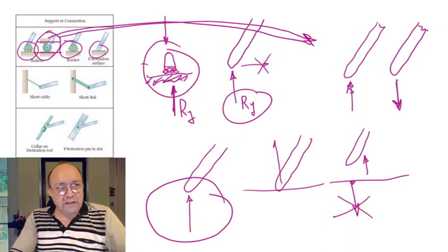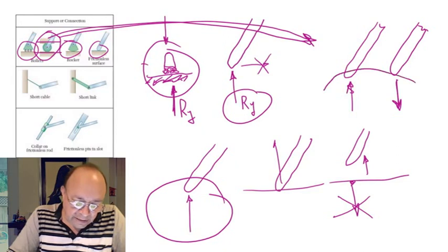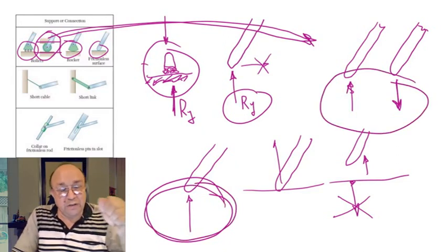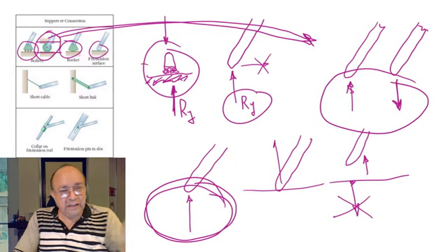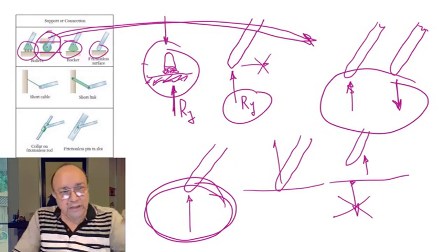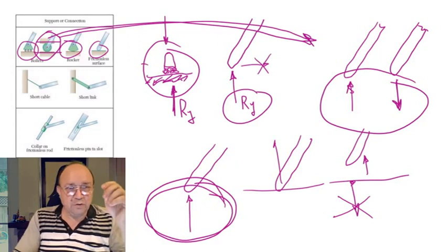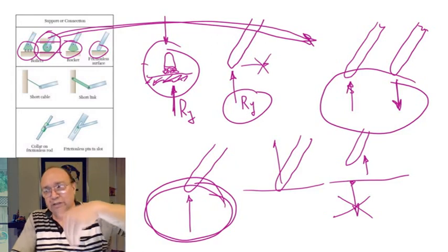That doesn't affect us much because since these forces are unknowns, when you set up the equations, you can put the sense of the force in any direction you want. At the end of the calculations, if you find that the result gives you a negative sign, you know that the sense you assumed was wrong, so you just put it in the other direction.